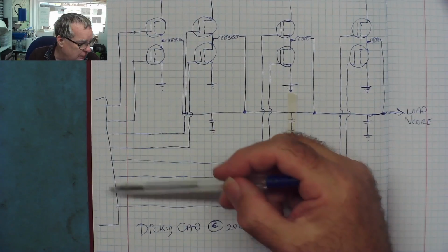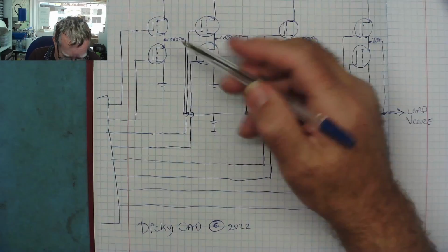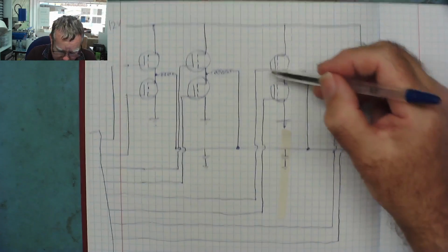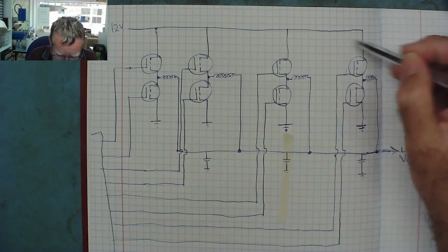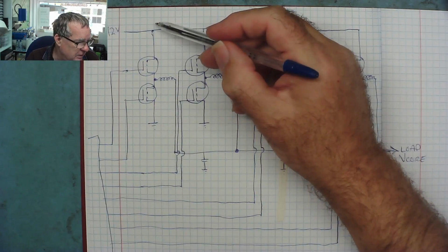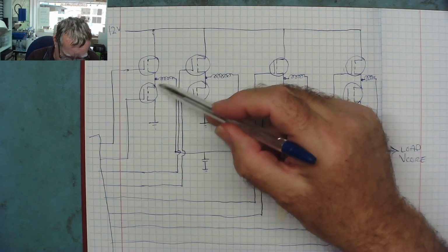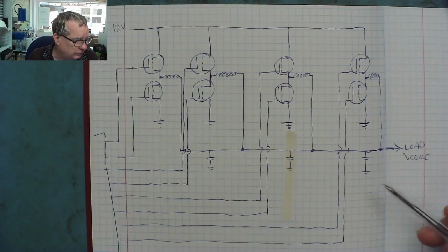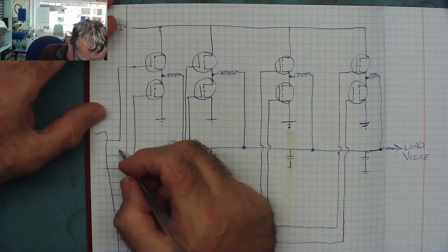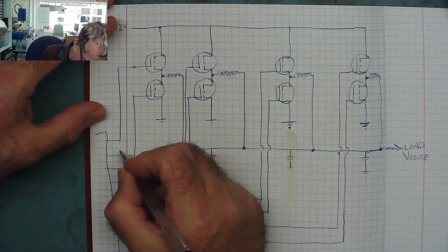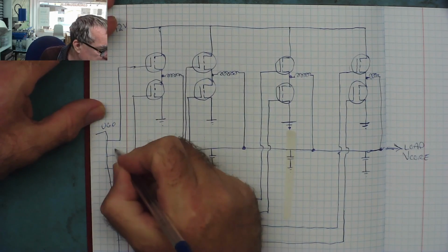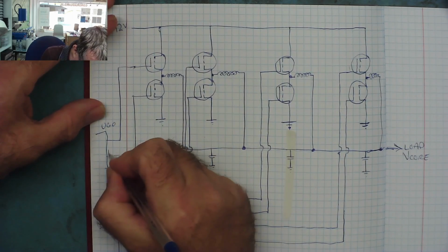This is the controller chip, and each of these is the high side MOSFET for each phase. And they're called high side because they connect to the 12 volts. And the other ones connected from the core to ground are low side, 4 of them. And the signals here would usually be called upper gate 0, because we start with 0 because we're computer minded, yeah.